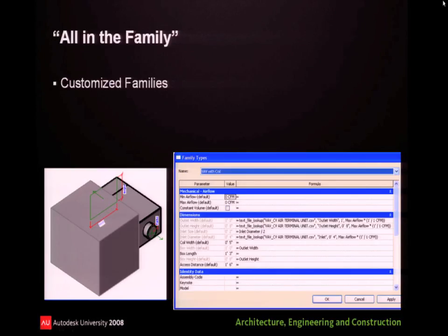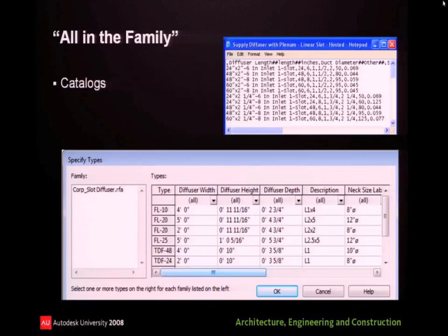it will flex that outlet to be a project-specific instance because it knows what's connected downstream of it to the air terminals. If later on we come back and change the CFM that's downstream in this box, the box will update, but right now the ductwork still stays the same, so we have to go back and change the ductwork. But it's still a nice progression into getting better at what we're doing with Revit MEP customized family.